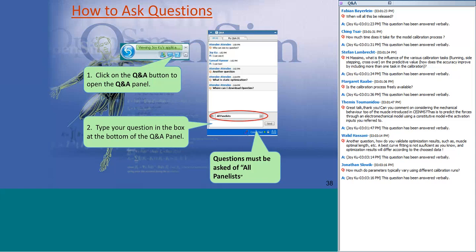So this is basically a little bit like the linear scaling in OpenSim. In this case, we are actually able to scale non-linearly the optimal fiber length and the tendon slack length to achieve a nice starting point. And then these parameters can be further adjusted in the calibrations, and they are only allowed to vary within 2.5% of their initial value.